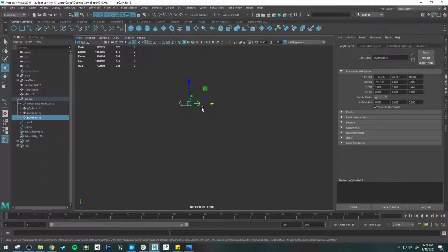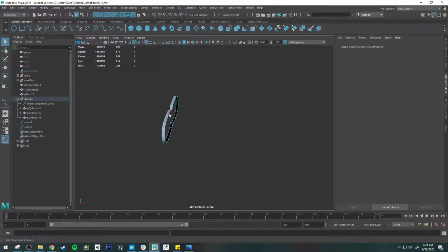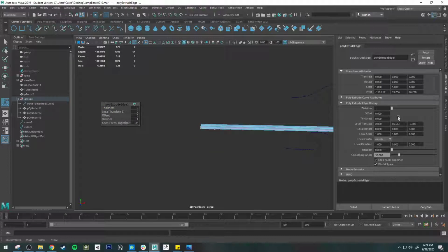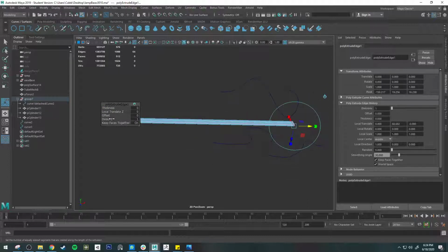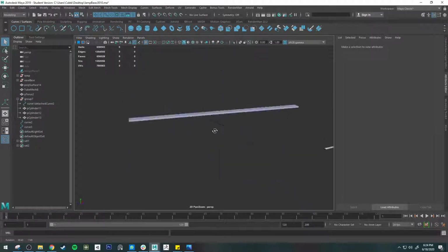It might be as simple as me just taking this object, let's rotate it 90 degrees, and then extruding this in one direction, right? If I just need it to be straight, right, I can just do that and then just add a bunch of subdivisions, right? And that's probably super easy to do, or way easier to do than this method.